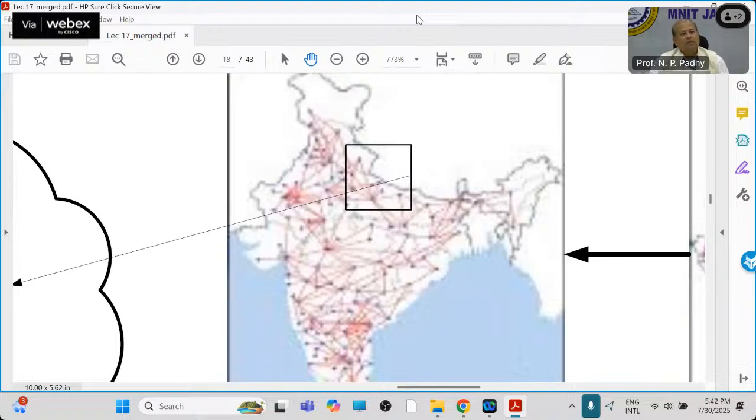And if there are millions of microgrids similar to IIT Roorkee in the country, MNIT will be one, right? Rajasthan University will be one, SMS will be one, IIT Roorkee will be another one, for an example. How will all the microgrids impact the national peak and national off peak? Then only you can do it, no? When I'm connecting a grid having a microgrid, I discharge my battery, I say there was a peak, so my battery helped. That is true. But to reduce the national peak, all the microgrids in the country must act simultaneously.